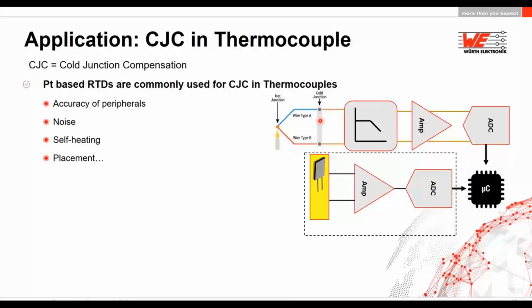So here, when you say that my sensor has an accuracy of X percent, you then add some peripheral devices, for example filters and amplifiers, which also add some noise and inaccuracy to your complete system. So at the end, sometimes you also have to recalibrate your whole system. The RTDs also might have the problem of self-heating, and they are also very design sensitive. So you have to take care of your design and invest a lot of time designing complex circuits.